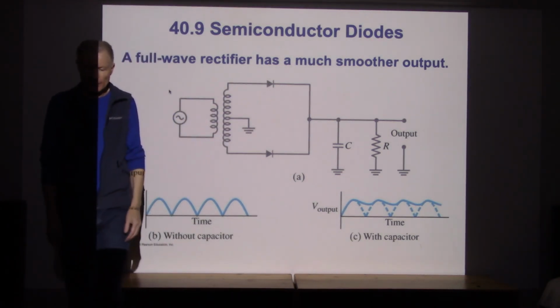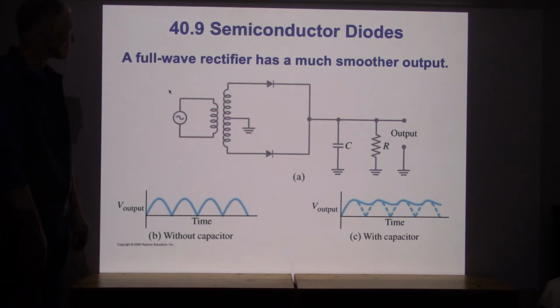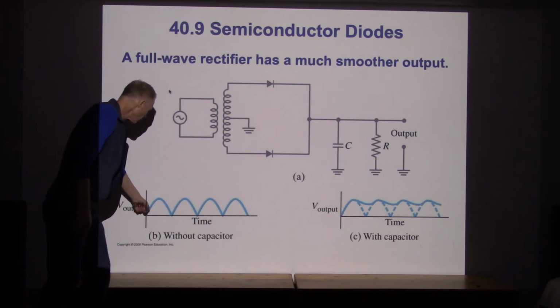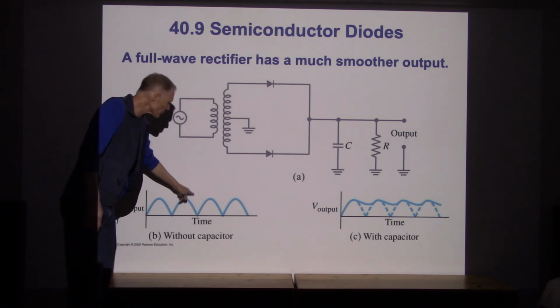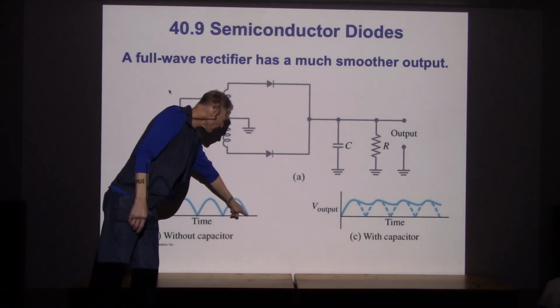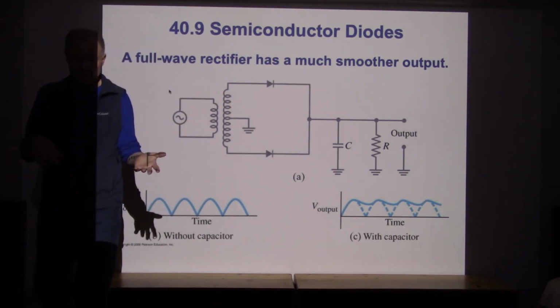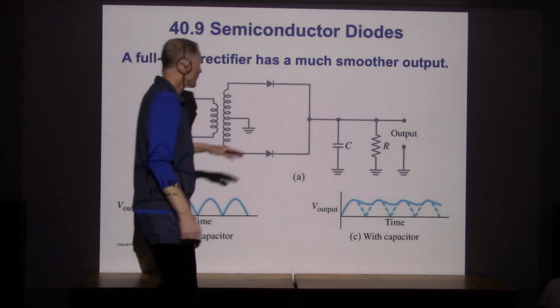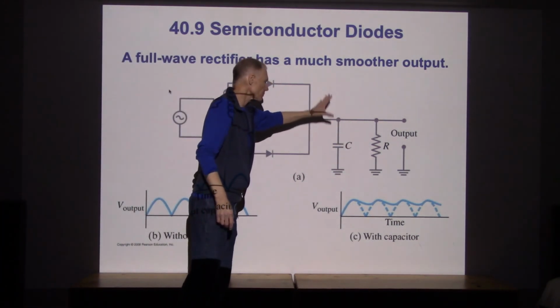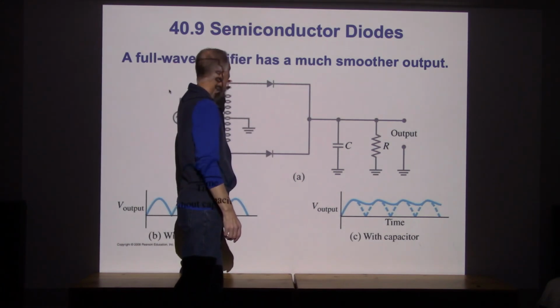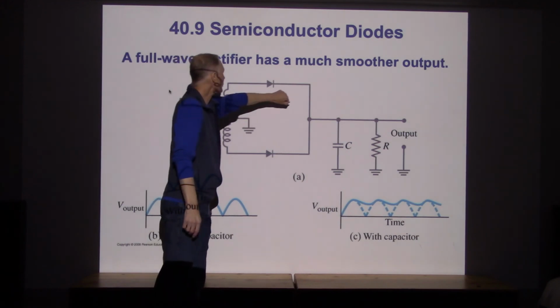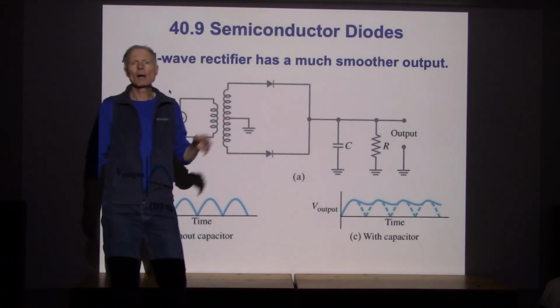So what that's giving us is it's taking something where we have the effect of the diode. So what the diodes are doing is it's allowing the AC effect to still take place, but it's only allowing the current to go in the forward direction. Notice that when we look over onto this part of the circuit, the capacitor, the resistor, the output, the current's only going one way. And it only goes one way because whenever the current tries to go backwards, it runs into a diode.